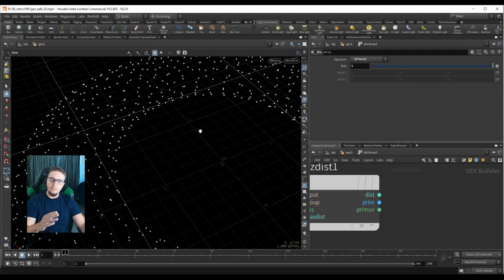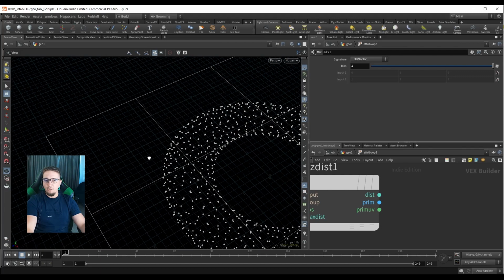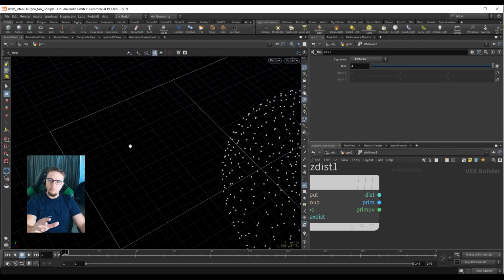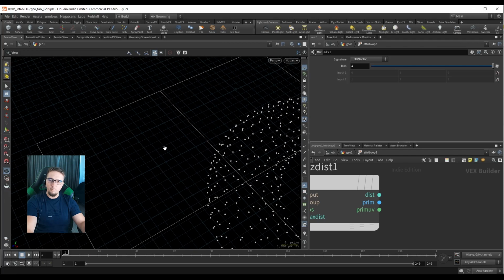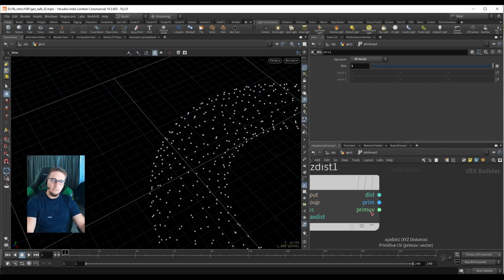So in Houdini, each primitive has this intrinsic UV attribute that goes from 0 to 1 for all of the primitives. So this is different than the regular UVs that we use for texturing and materials. If we look at just one of these primitives, so one of these squares, each of these has a separate intrinsic UV coordinate that we can use to determine where the point lands. So we can imagine that it's something that goes from 0 over here to 1 over here, and then another 0. So it's going to use these coordinates to find the position where our point lands. So again, all primitives have this information, this intrinsic UV. But long story short, this here is just the position where they land on the primitive.